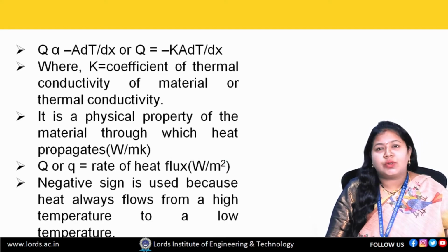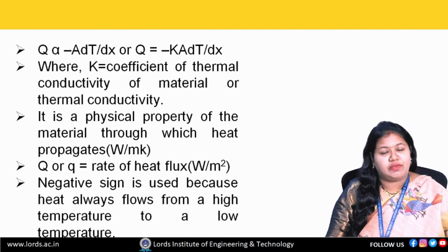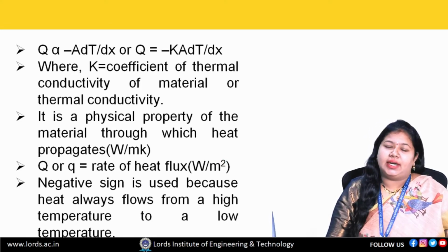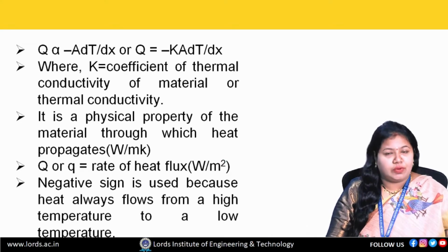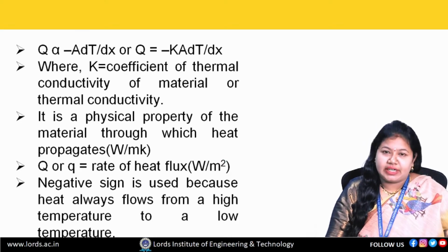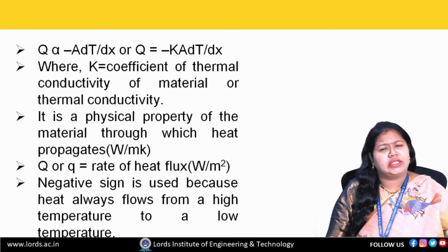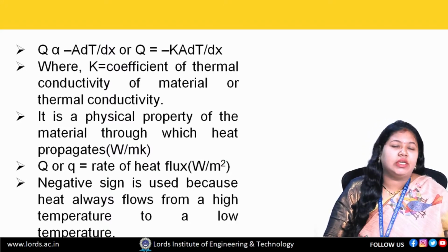Here also we find the heat flow rate in liquids or fluids by the formula Q = hAΔT. Here Q stands for heat flow rate, h stands for the coefficient of convective heat transfer, A stands for cross-sectional area, and ΔT, also termed dT, is the temperature difference or change in temperature from the body to the surroundings.